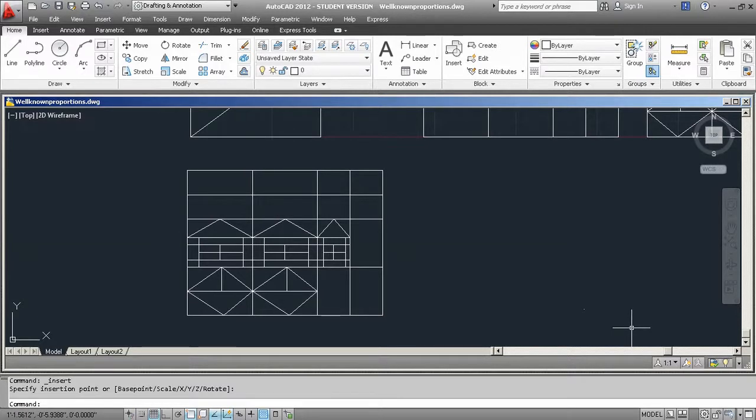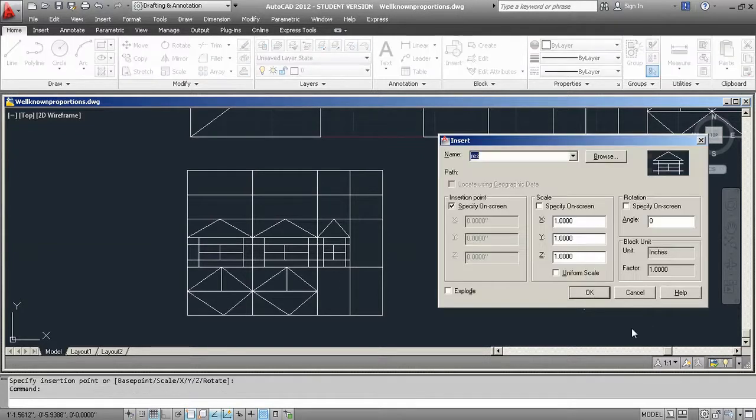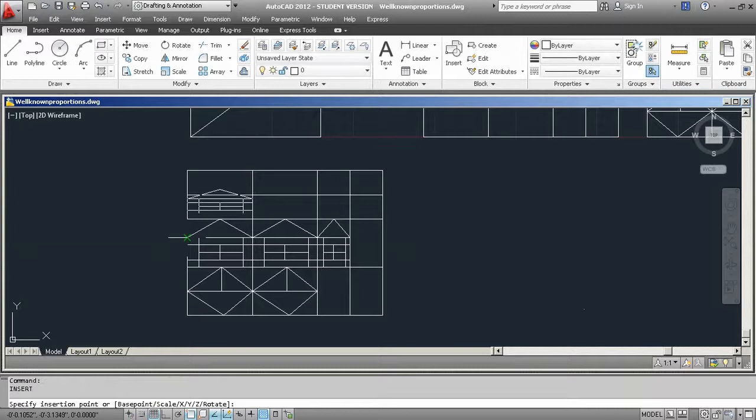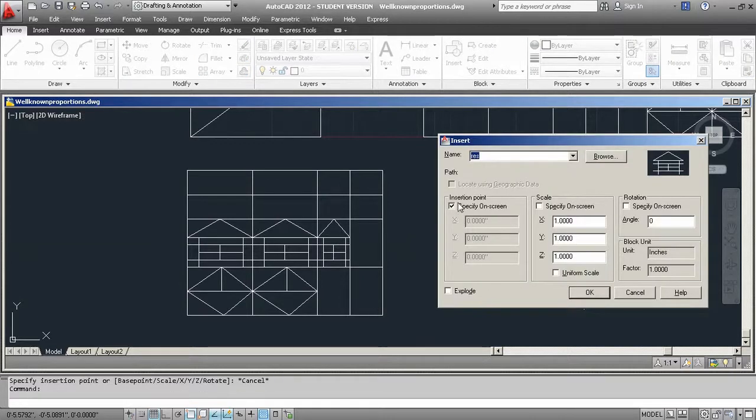We're going to use the same technique and make blocks and insert the objects proportionally in either the X or Y directions. Making blocks and inserting at different proportions is one of the smarter ways of doing this project using AutoCAD. Of course, you can draw everything freehand, but perhaps it's much easier to make blocks and insert them in different proportions. It's more productive too.